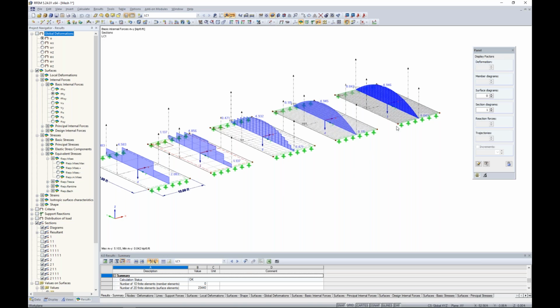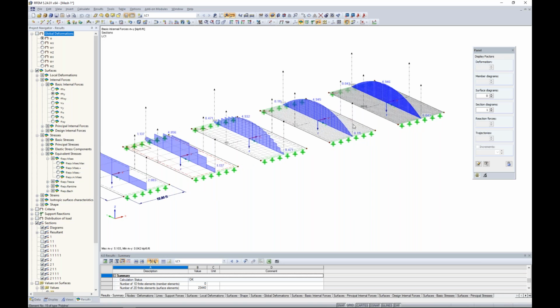So for example, these two elements here, the one on the left has about 1/3 the FE mesh than it does on the right, but yet our results are only changing by 0.001. So it's kind of this happy medium here to find out the right balance of when we are able to refine our FE mesh to gain accurate results, but not too much so that our calculation time is increasing significantly because we've added all these additional elements.